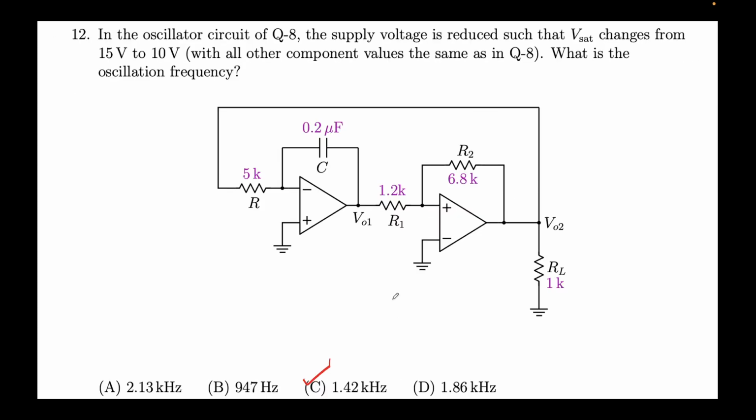Right, so up until here we have discussed a lot of problems related to Schmitt trigger, especially focusing on the low and high trigger points, which were also called the trip points. And we saw, especially in the previous sets of problems, how we can integrate two stages. If the first is an integrator and the second is a Schmitt trigger, here we can generate an output, a square waveform. Here we can generate a triangular waveform, right?